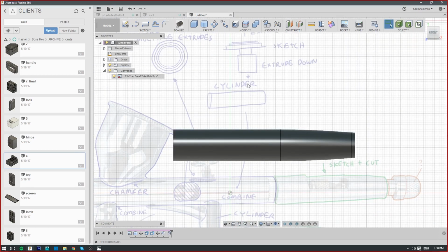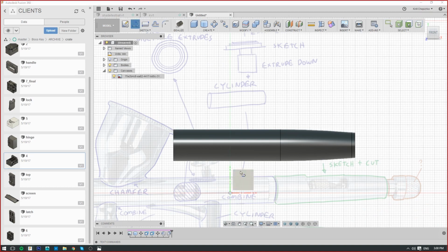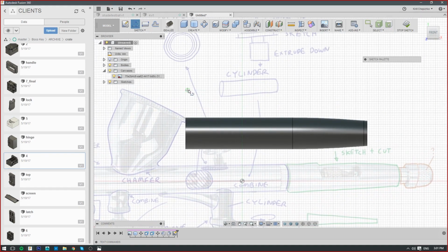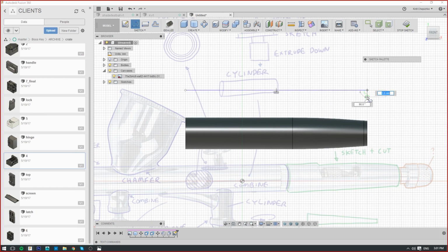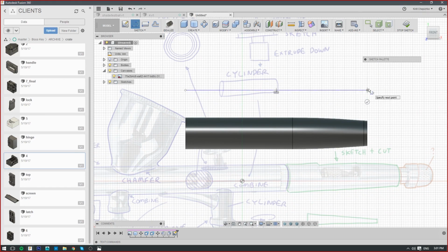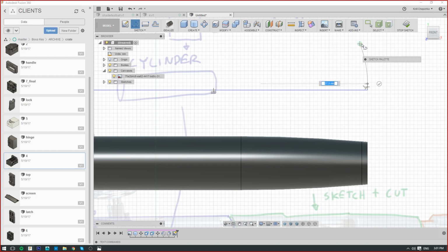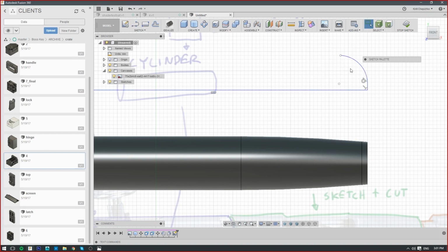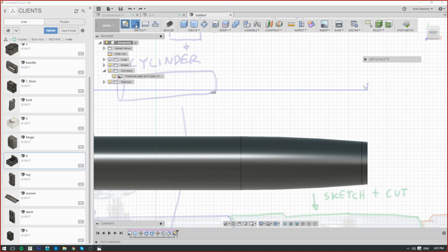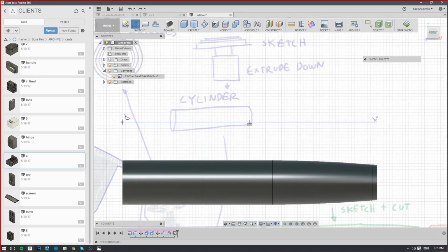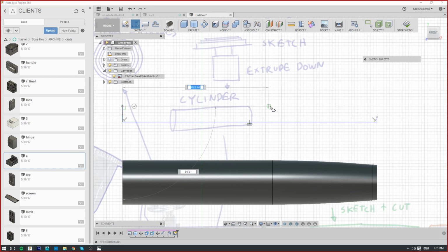The other way would be to sketch it out with a revolve. You define the length, and this will also be your center, and then you sketch out the profile that you need. Just like with the pen tool in Photoshop, if you click and drag, you can start doing the curve. But I actually don't like the lack of control there. This is going to be half of our diameter. Because I clicked and dragged, it gave me that control.